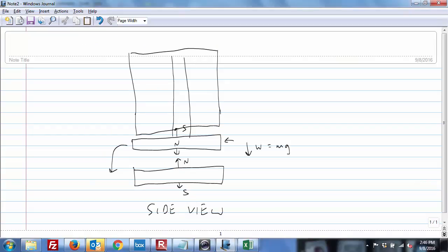And obviously when the wind blows from this direction, some of that energy is turned into spinning, which is what you want, but some of it also is turned into a bending. And if you have a shaft, you're going to have some kind of bearing up here, some kind of bearing at the bottom.